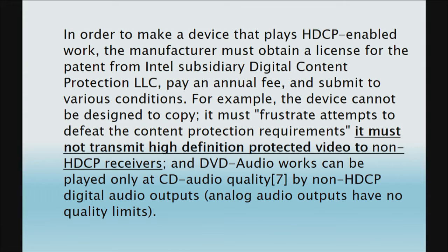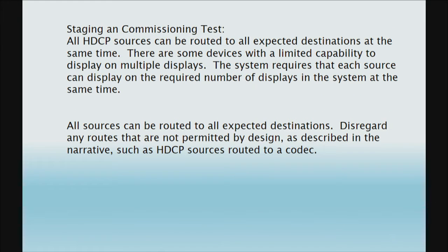And if you think about it, it's kind of wordy if you've never looked into this, but there are all the things that are happening before the keys are exchanged in this HDCP land, and it can have a delay, especially if you're buying some inexpensive products that aren't working well in this world. So a few things I mentioned here: when you're checking these systems at commissioning time, make sure you're turning on every expected source. Everything's there and you're seeing it where you want. Because if this new display comes on and it wasn't tested and it hiccups, you're going to lose your HDCP key, and then you're not going to have an image.